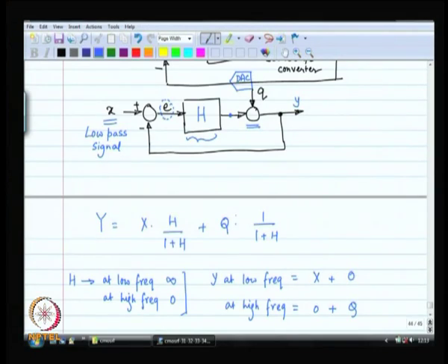This is some sort of an integrator, which means you are doing some sort of addition, sigma. Okay. And you have got a subtraction over here. So, that is the delta. Now, some people call it delta sigma because the subtraction happens before the integration and so on. It really does not matter what it is called. At the heart of it, it is a feedback control system.